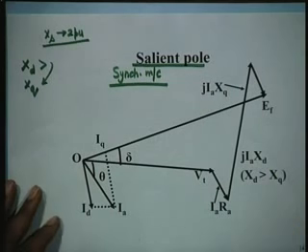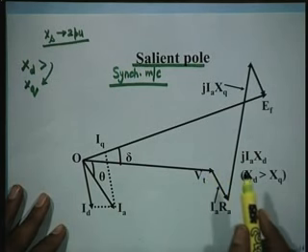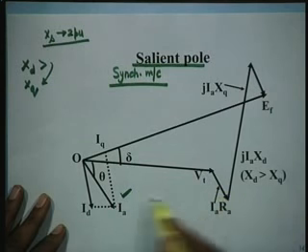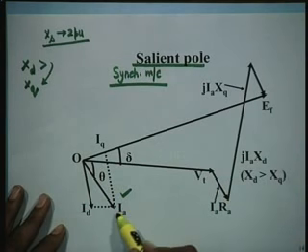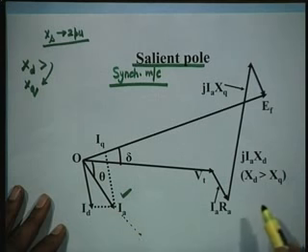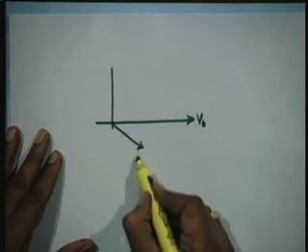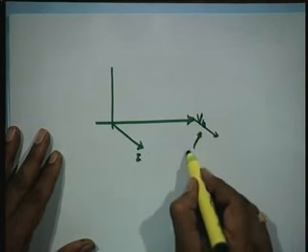Now, we come to the phasor diagram. This Vt is horizontal, it may not look so in the figure, it is a reference phasor. This is the current, the resistance drop has to be added in parallel to the current, and then this should be 90 degrees to this. Obviously, the diagram has not been properly drawn. I think we can draw it properly. Of course, it is not to the scale.